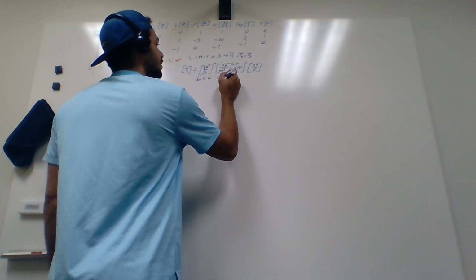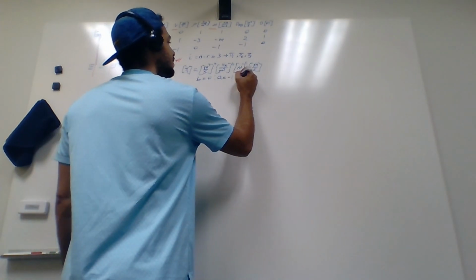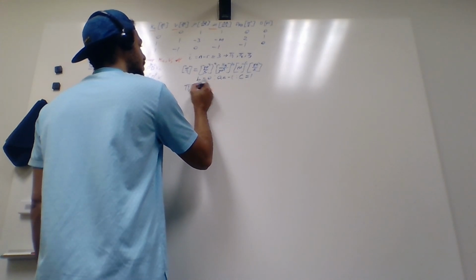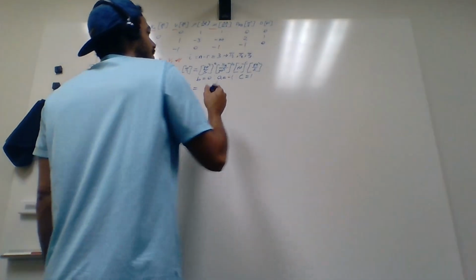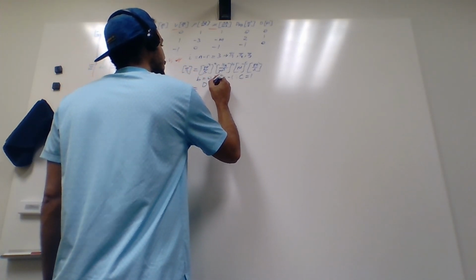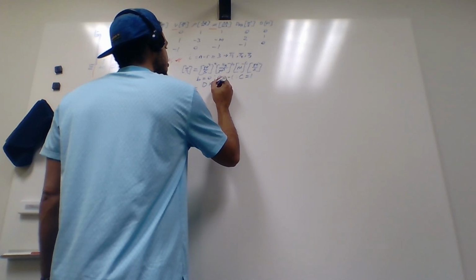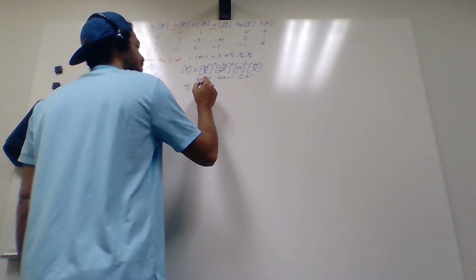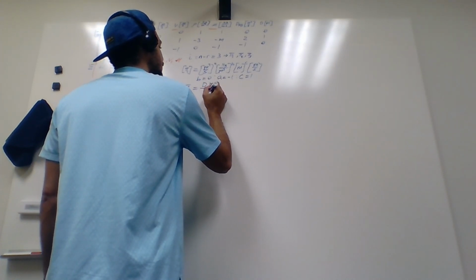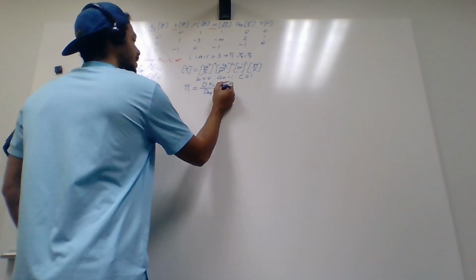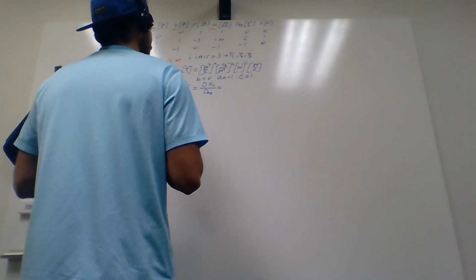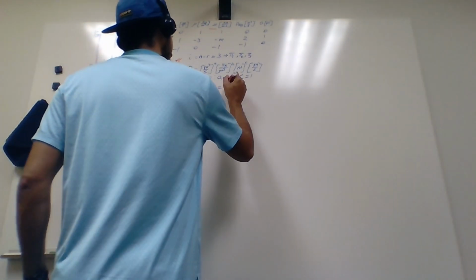So A is equal to -1 and C is just equal to 1, which results in pi 1 equaling the diameter times the mass transfer coefficient divided by the diffusivity from A to B. And that expression, through definition, is defined as the Sherwood number.